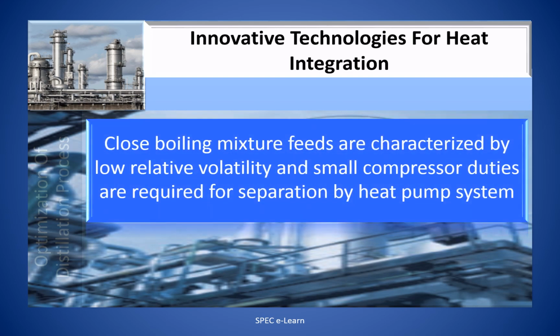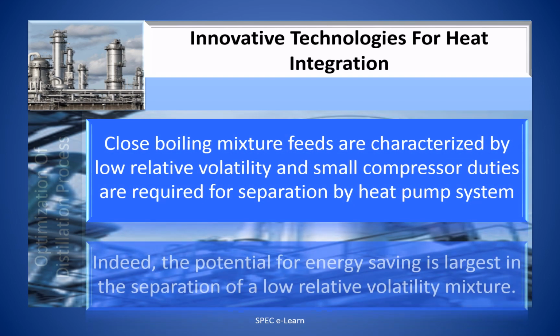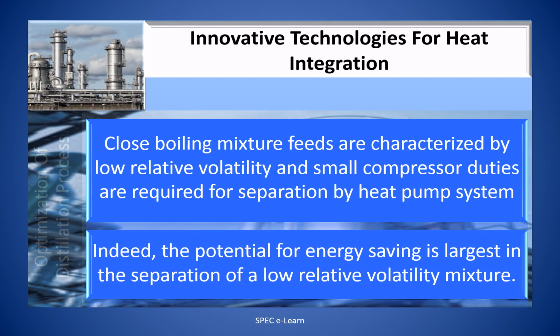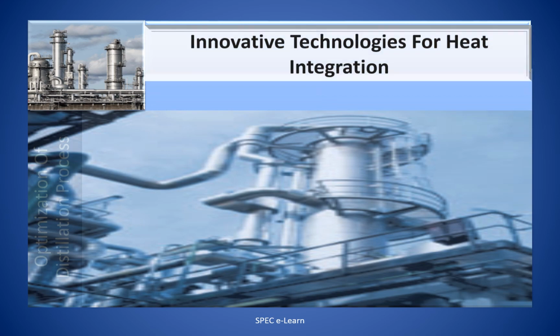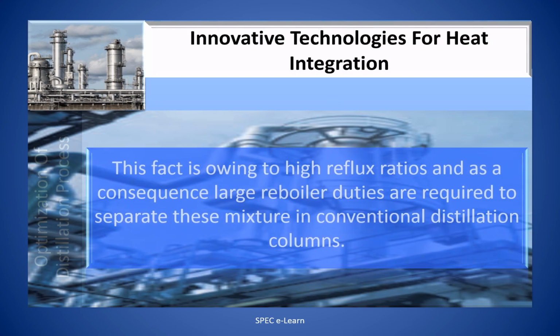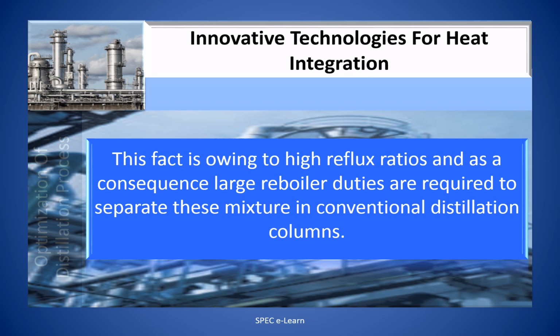Close boiling mixture feeds are characterized by low relative volatility, and small compressor duties are required for separation by heat pump system. Indeed, the potential for energy saving is the largest in the separation of a low relative volatility mixture. This fact is owing to high reflux ratios and as a consequence, large reboiler duties are required to separate these mixtures in conventional distillation columns.